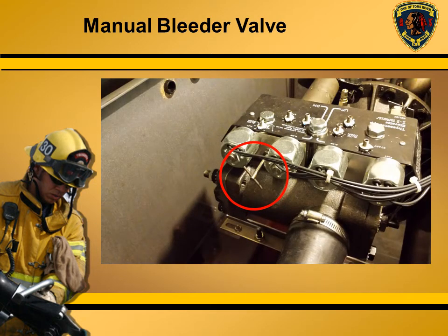The bleeder valve is usually a small T-handle needle valve. The more you open the valve, the faster the elevator car will drift down. The car will not drift down any faster than it would under normal conditions.